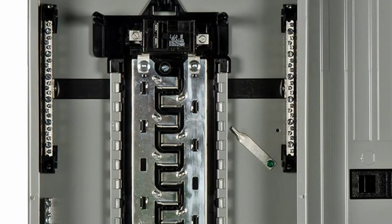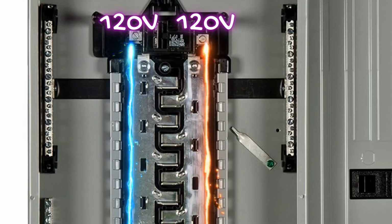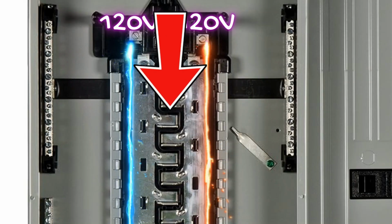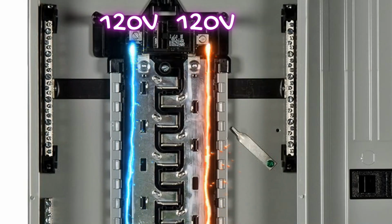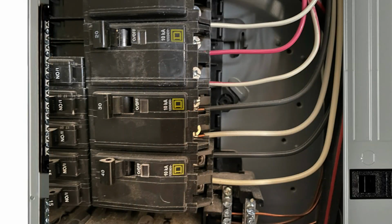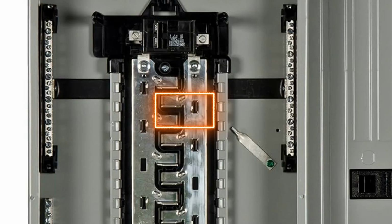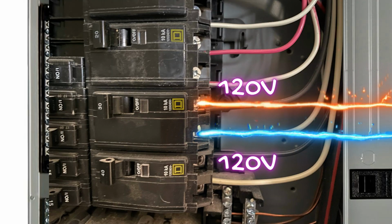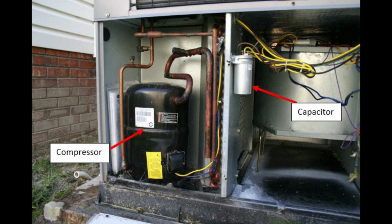Now, behind all those breakers, we have two bus bars, and each 120 volt leg from the transformer out on the telephone pole connects to each bus bar. Now, you can see in the middle, these bus bars have this sort of overlapping pattern. And that is because when you put a double pole breaker into an electrical panel, each terminal of that breaker is touching a separate bar. And so that breaker is putting out 120 volts on each terminal, 120 from one bar and 120 from the other bar. And this is the 240 volts that we send to our compressor, where all the magic happens to create cold